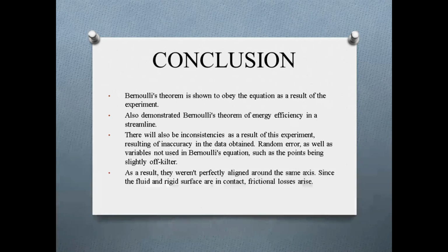So I would like to talk about the conclusion for this lab. In this lab, Bernoulli's theorem is shown to obey the equation as a result of the experiment. We may deduce that it is accurate for fluid flow based on this. As the segment's area shrinks, velocity increases and the pressure decreases. The experiment also demonstrated Bernoulli's theorem of energy conservation in the streamline.